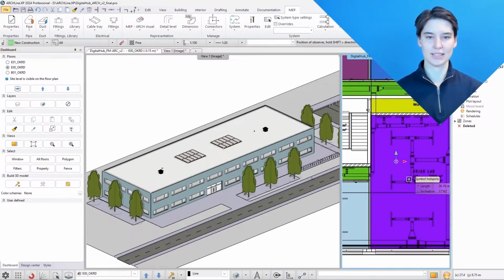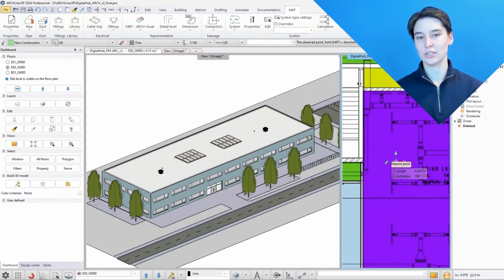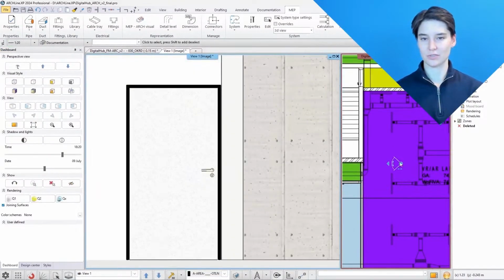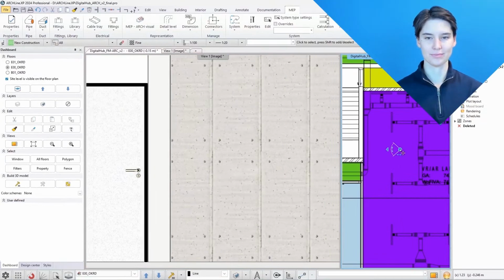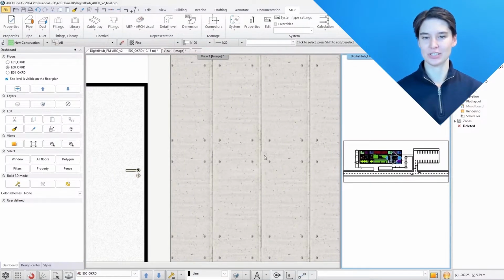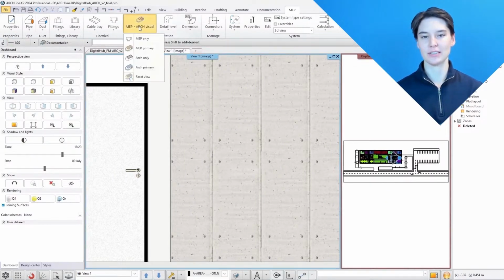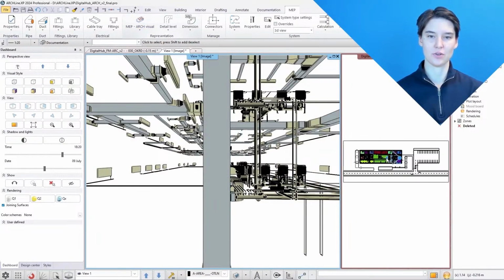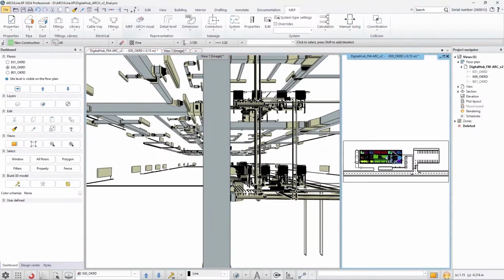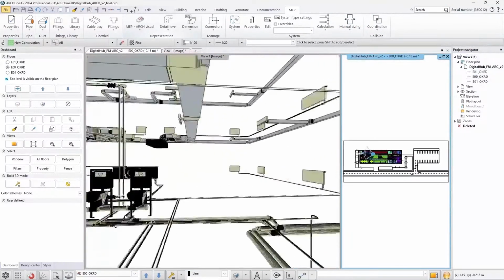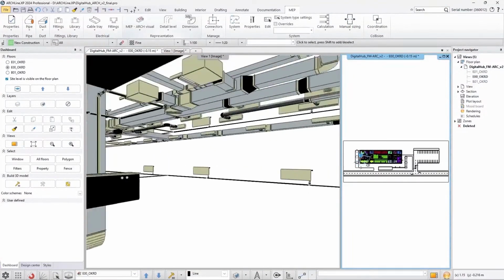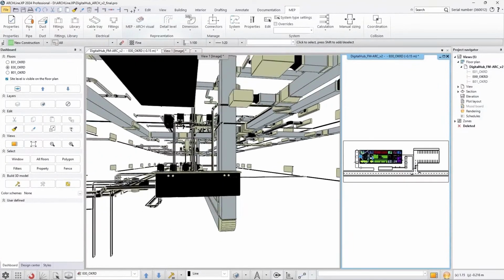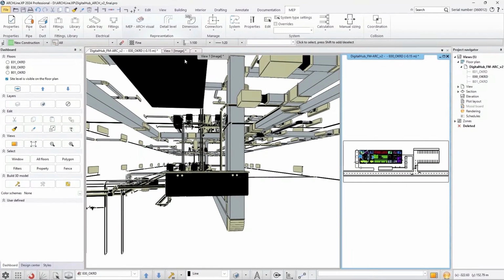Additional notes can be added to the 3D BIM model to ensure all of the measurements are clear for each discipline. Elevations and sections can also be used to explain and detail the layouts for anyone who needs access to the information. Using the Walk tool, you can navigate through a model as if you were walking through it. To walk through the model, drag the eye marker in the direction in which you want to move.